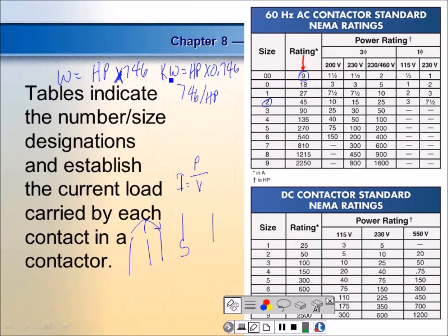And why do you need to know this? If you deal with motors, you're going to run into both of them. And eventually, to me, kilowatts is actually better because it's telling you how much it's going to cost you to run the motor. Over here, we say a 30 horsepower motor. How much is it going to cost you to run that? Understand what I'm saying? So we have to kind of figure it out over time. Of course, if you deal with motors a lot, you have a pretty good idea. But, to start off with.